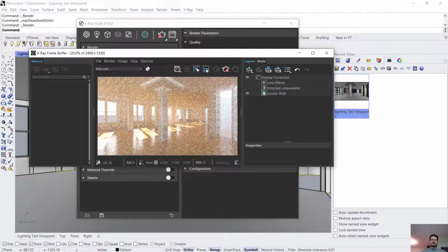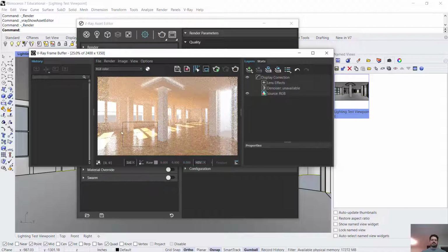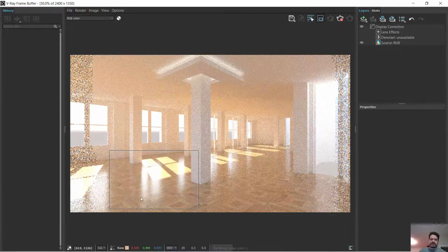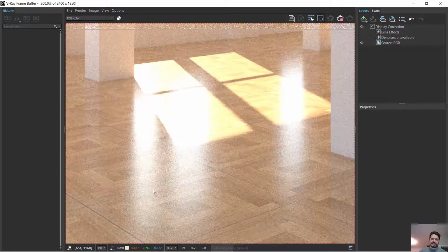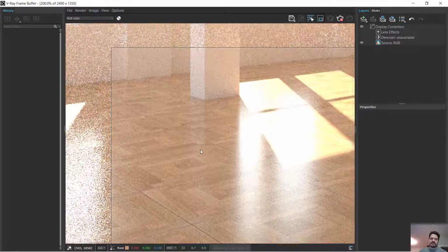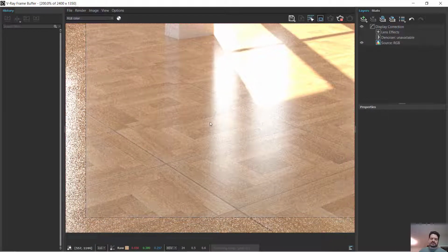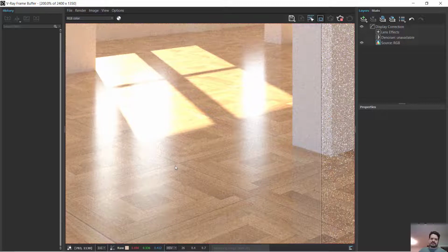And I'm also going to turn on in my viewport something called region render, which allows me to draw. Let me stop that. Region render allows me to draw or resize a region, so I'm only going to be rendering that region. So now if I start a new render, it's limited to that part of my scene. So it goes much faster and I'm able to see more detail in my scene. So as I scroll in, yeah, that's something. Starting to see some sense of my texture.